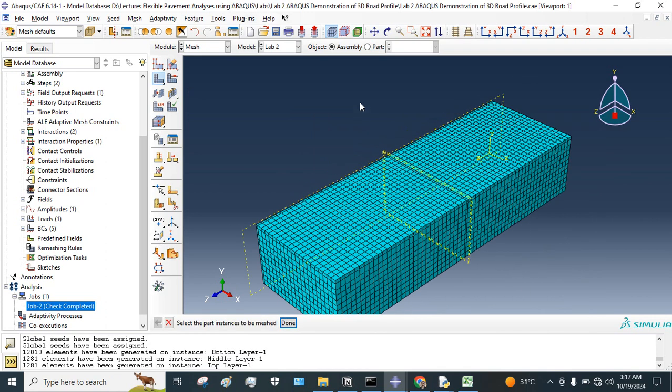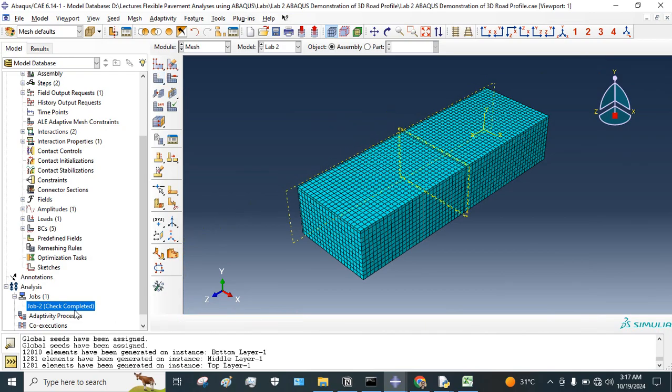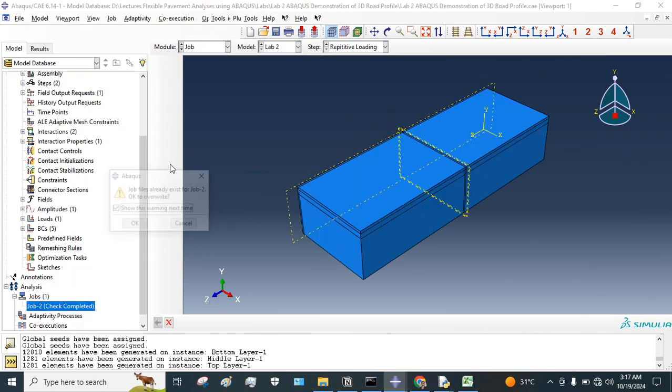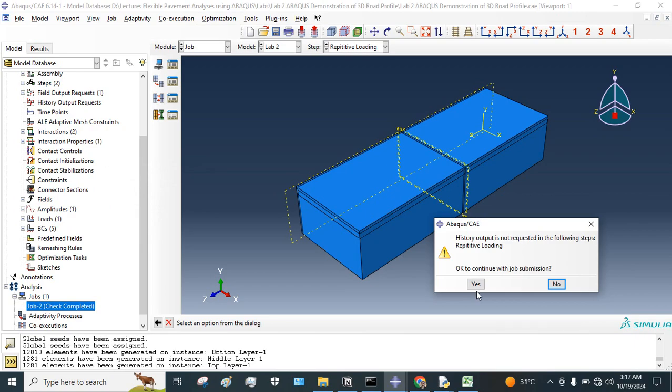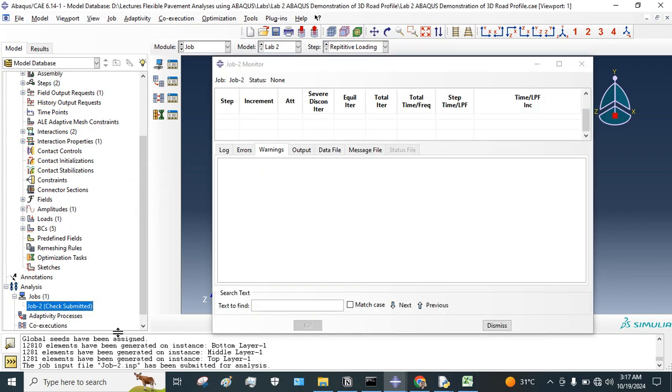So we have approximately 14,000 elements. It's not a bad idea. And let's apply the data check again. So that aspect ratio warning will be removed, right? And we will get a smooth model. Only the warning about material will be available, which is an informatory warning.